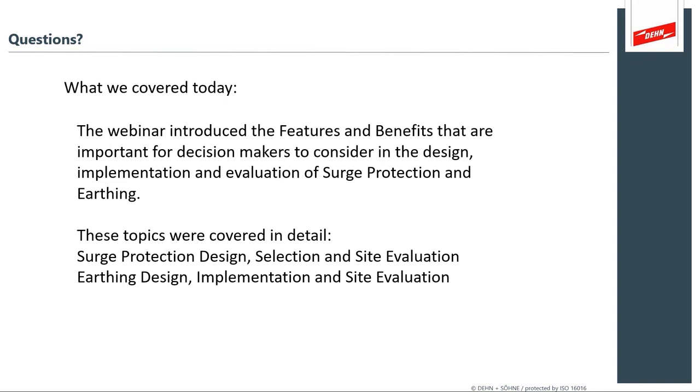In normal maintenance cycles, it's probably once a year is sufficient to go through and look at your SPDs. But again, they don't necessarily last forever. So sometimes I hear things like, well, every 10 years you might want to replace your SPD. And that might work for somebody in a modest climate. If you're in southern Florida where I'm at, I had heavy thunderstorms just the other day, so I'm paying attention to my surge protection devices every year. So it definitely depends on your level of risk that you're willing to absorb, and the type of environment that you're subjected to.